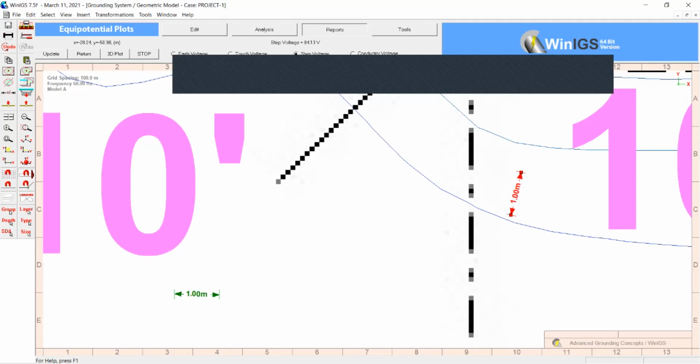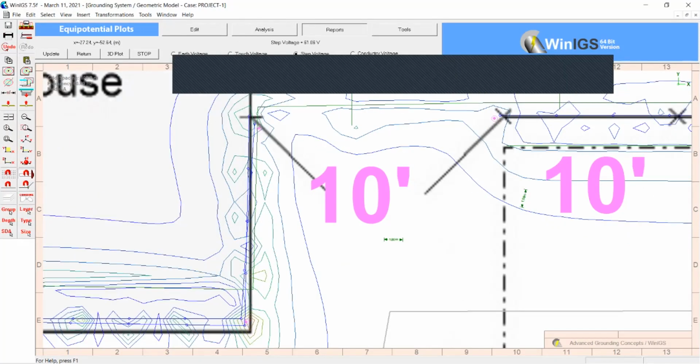Yeah, so within this line, voltage is the same. Now the way I put the scale here, voltage is 70.5 volt, here 57.5 volt. So what will be the difference? That will be the step voltage here. Okay, so step voltage usually is not that high.